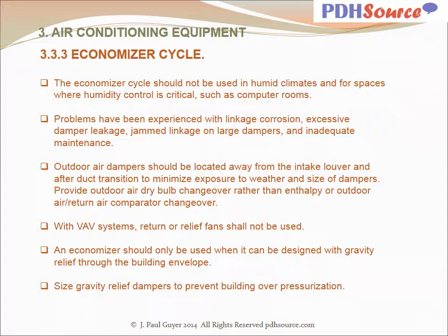Outdoor air dampers should be located away from the intake louver and after duct transition to minimize exposure to weather and size of dampers. Provide outdoor air dry bulb changeover rather than enthalpy or outdoor air return air comparator changeover. With VAV systems, return or relief fans should not be used. An economizer should only be used when it can be designed with gravity relief through the building envelope. Size gravity relief dampers to prevent building overpressurization.